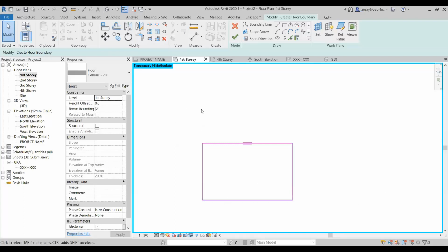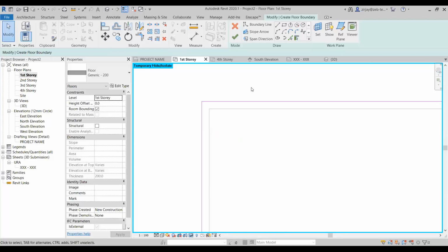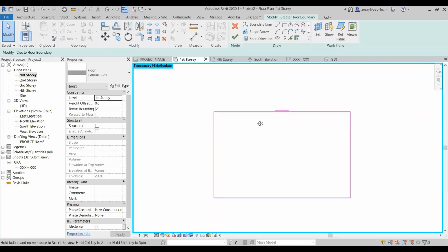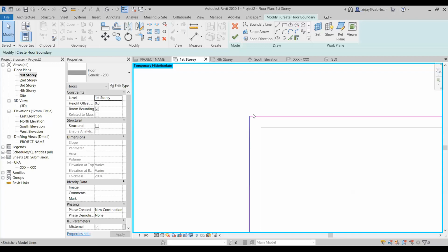With that, you can just quickly press tab, and it will follow that outline, and then you can just offset it eventually. Okay, so it varies from case to case, whichever tool you use. Just make sure you're always up to the exterior side of the wall when you're creating floors.